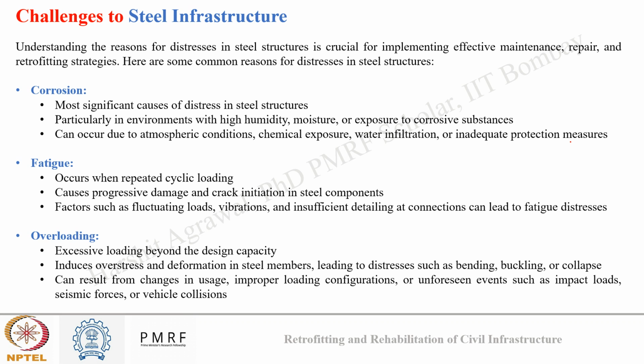The second reason for distress in steel can be fatigue, that occurs due to repetitive cyclic loading. It causes progressive damage and crack initiation in the steel components, and it can result from fluctuating load, vibration, and insufficient detailing and connections, which can lead to distress.